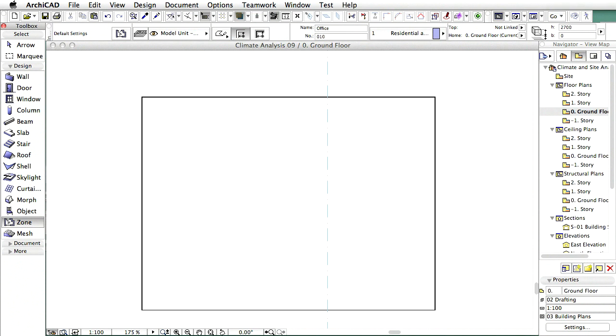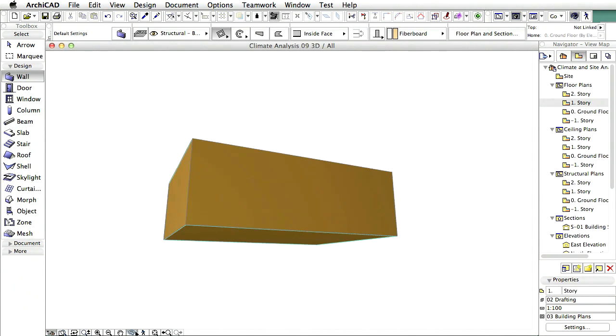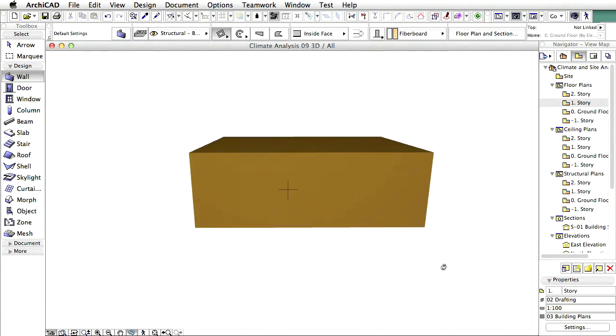Let's also insert a 3D zone. These are all standard ArchiCAD elements. Here's our simple building in 3D. We used very thin, 10 mm thick exterior structures, so technically this is a so-called paper box space, as its sole purpose is to define an internal space.